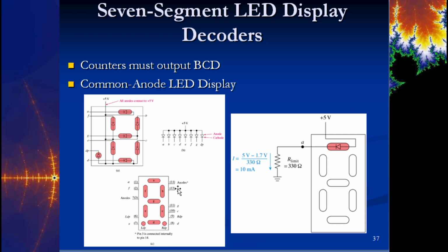So having that extra tenth of a second on the scoreboard, that extra resolution, is beneficial. And so you would have to switch the way you were displaying your 7-segment displays to reflect that, now the ones or the tens is in a different position, and then I'm also showing tenths. And that's what the decimal point will allow you to do.